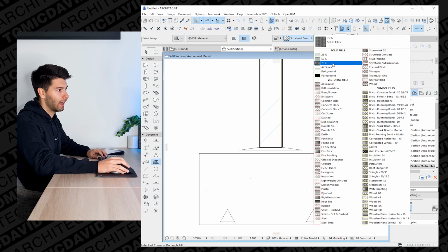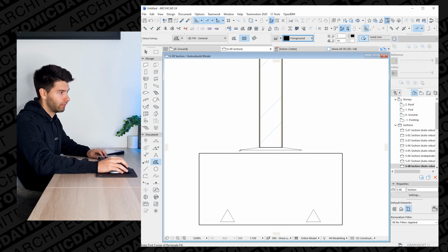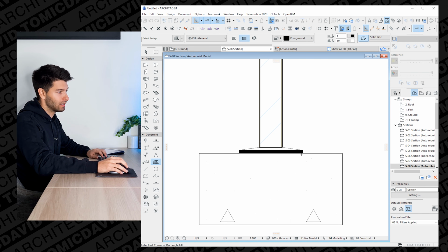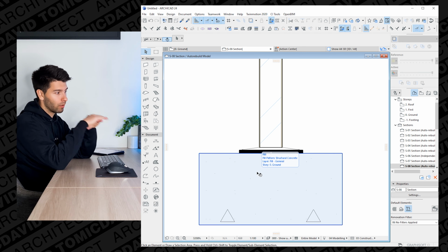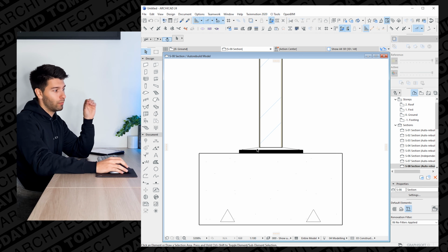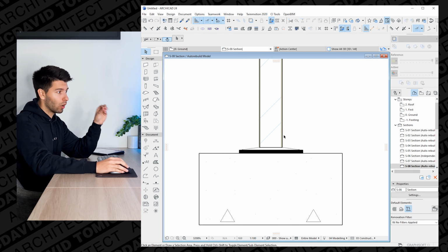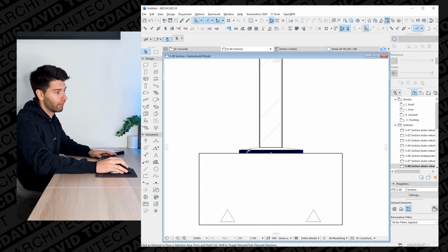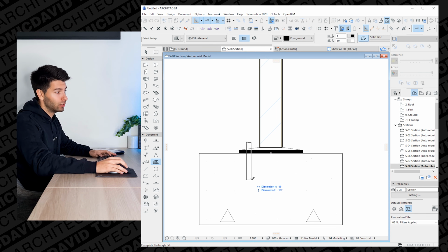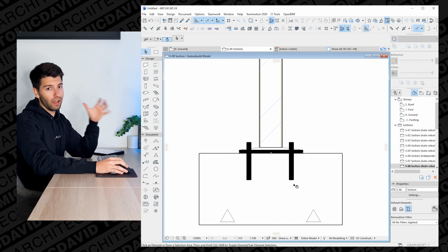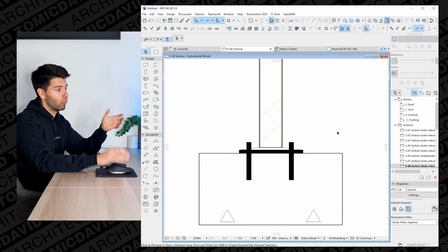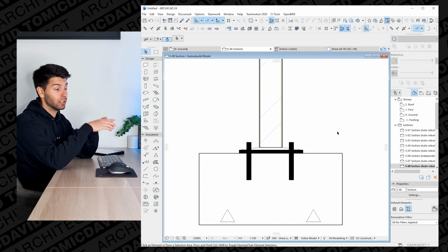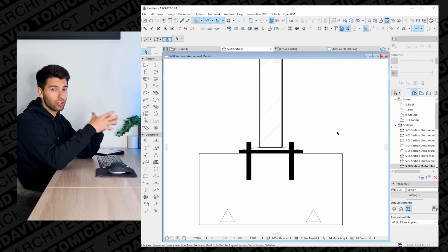And then we would have a little bit of grout filled in underneath this section of that base plate. So the grout would be on top of that concrete footing. Then there would be a base plate for that steel column, and then you'd have the steel column up above. What would then happen is there would be 2 bolts bolted on site as that steel column is put into place. Those anchors there, unlike the timber, would most likely be a chemi-anchored bolt because it is a structural element